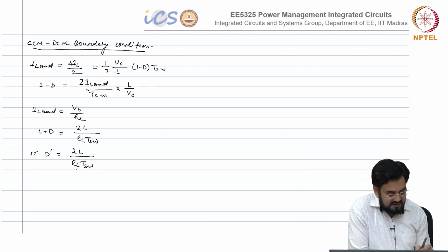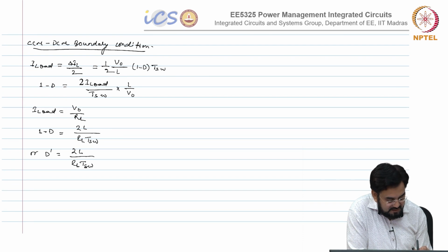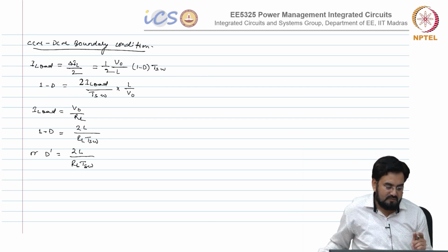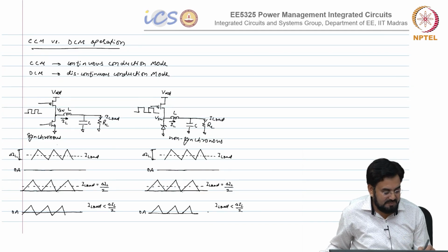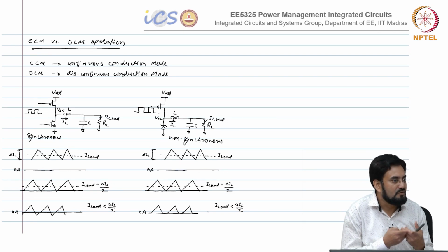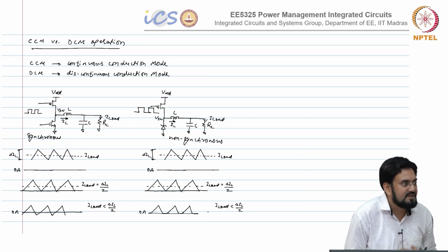Okay. So, if you are increasing the load current, decreasing the load current for the same switching frequency, so what exactly will happen actually? You will be outside the boundary, above the boundary, and as you reduce, you hit this point. So, what is happening actually, if you see, you do not allow this negative current, which means your off time has to be reduced to keep in the CCM.